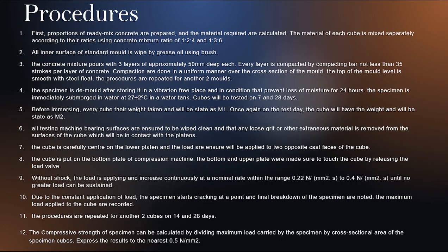Without shock, the load is applied and increased continuously at a nominal rate within the range of 0.2 Newton to 0.4 Newton until no greater load can be sustained. Due to the constant application of the load, the specimen will start cracking at a point and finally break down. Those are noted, and the maximum load applied to the cube is recorded. The procedure is repeated for another 2 cubes on 14 and 28 days.